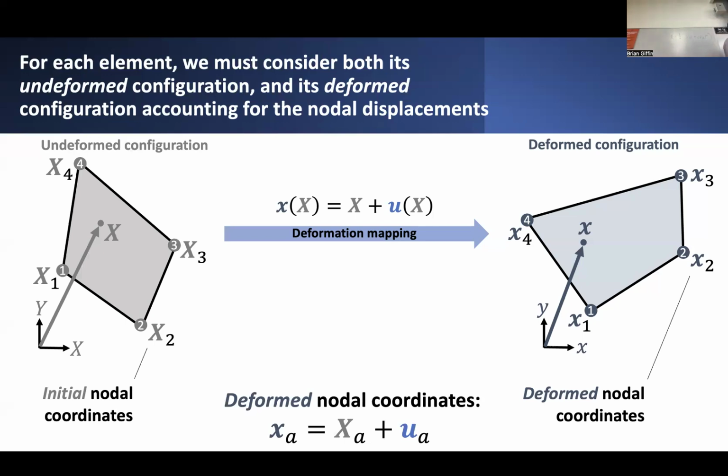So, back to the subject of nonlinear analysis being an inherently iterative process. We have to make an initial guess of what we think the displacements of the structure are, so that given this guess, we have some guess for what the deformed state of the structure is going to look like. From that, we can come up with descriptions of the strain in this assumed deformed configuration. We can determine the resulting internal forces from that deformation, and then verify: does it actually satisfy equilibrium?